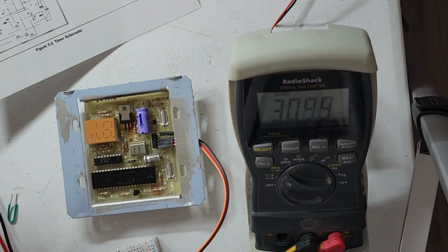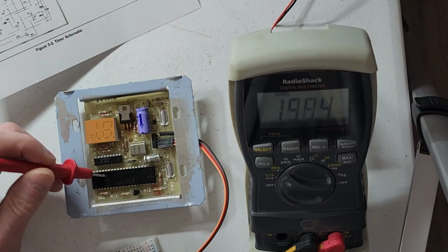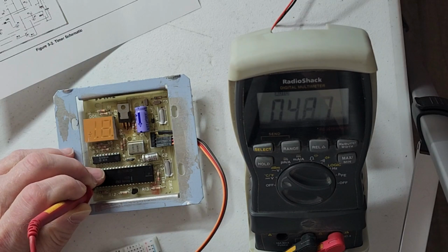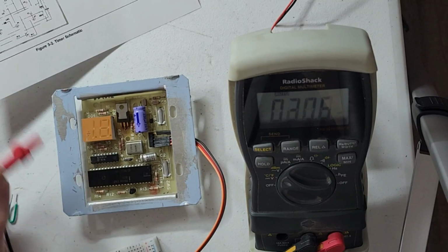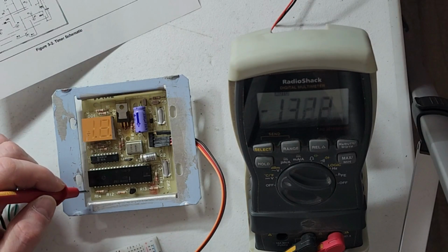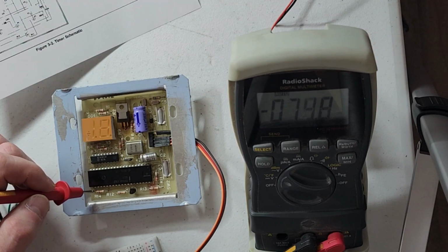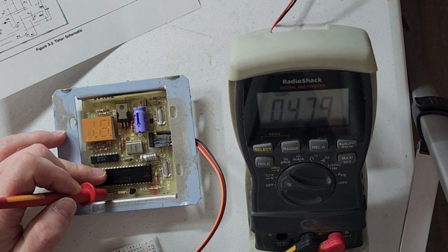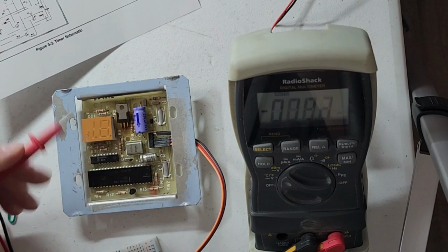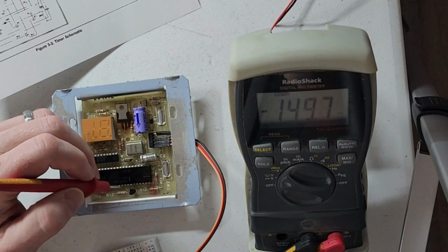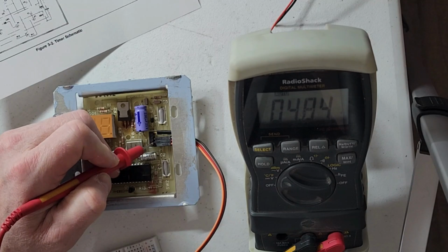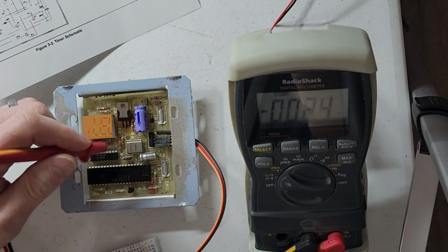Interesting. So that tells me that pin 21, I believe this is a 40-pin chip, so pin 21 is at 4.8 volts on the base, well, through a resistor. One of these resistors, I'm going to guess. I can kind of see the traces through this one right here. 4.8 volts to the base of the transistor is going to turn it on. So this thing's trying to turn the pump on, which it is, because right here's the pump pin. We got 4.8 volts. But it shouldn't be trying to turn it on.